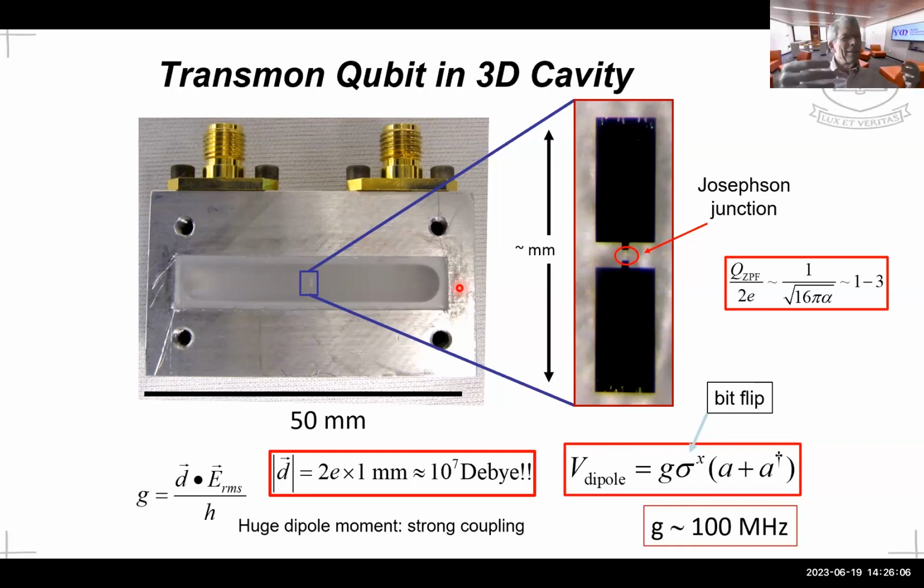It's a continuum. And the energy is stored in the electric field squared integrated over this volume and the magnetic field squared integrated over this volume. If you take the coordinate to be the electric field at this point, the square of that coordinate is proportional to the integral of the electric field squared everywhere. So you can kind of map it onto an effective lumped element.